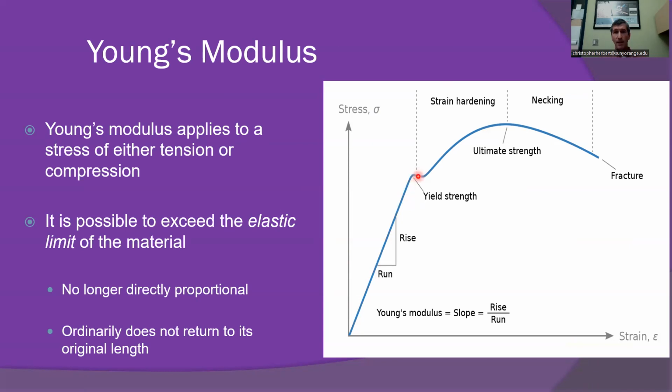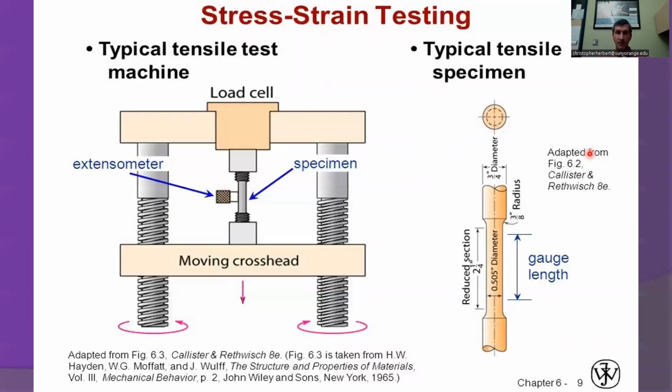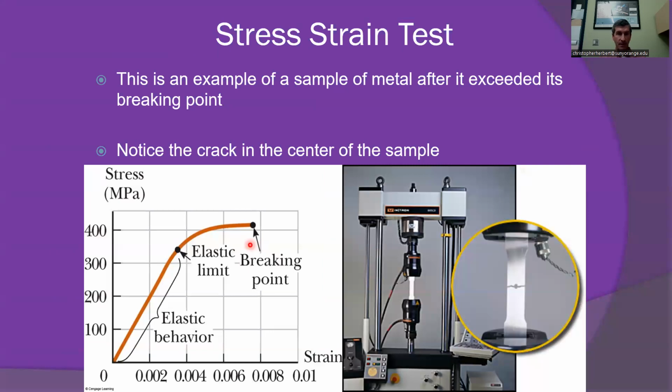It would go beyond its linear realm where it began to deform non-linearly, but then would actually stretch and then finally fail down here. This material is a little more brittle that's being tested here, where we'll actually reach this non-linear realm right here, and then fail at not much more stress above the region at which we experience elastic behavior.